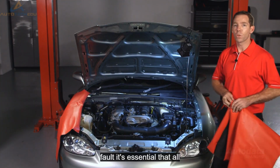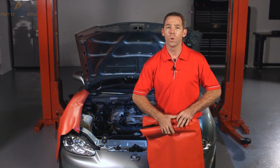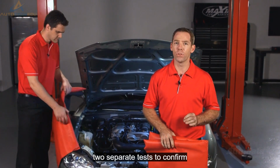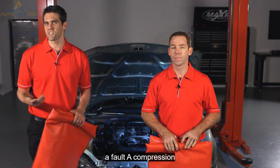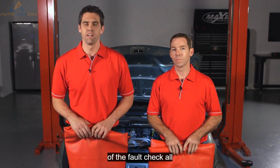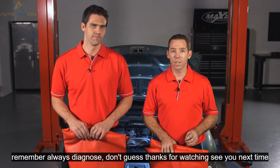It's essential that all mechanical checks are carried out when performance testing an engine. Where possible, try to use 2 separate tests to confirm a fault. A compression loss may be a symptom and not the root cause of the fault. Check all ancillary systems to confirm this. Remember, always diagnose, don't guess.